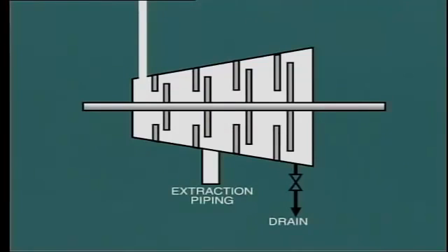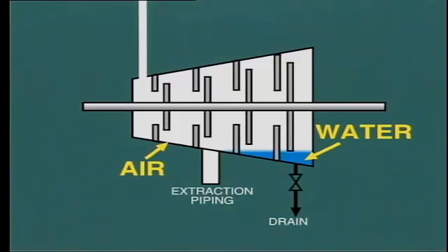During startup, all of the turbine and any pipework which is connected to the shell, such as extraction steam piping, is under vacuum. We must be extremely careful that any operation of drains, for example on extraction lines, does not allow air or even worse, water to be sucked into the body of the turbine.